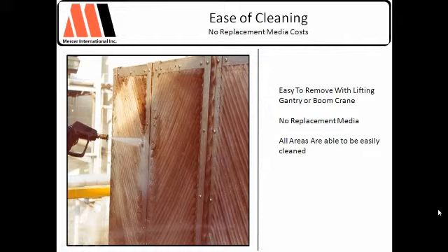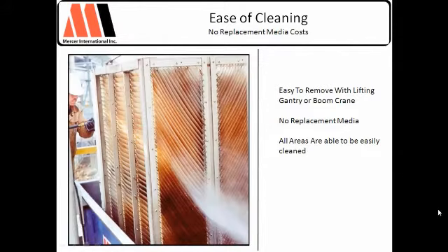Here's a picture of a guy in the entry area of the coalescer. The maintenance guy is cleaning up, and the next slide shows what a cross-flow, flat plate, short width design with chimney zones does. He is a 5-foot distance here, and there's still velocity coming through there. We can clean from this part of the separator, from this part. We can clean from this part of the coalescer. We can clean from the back of the coalescer.